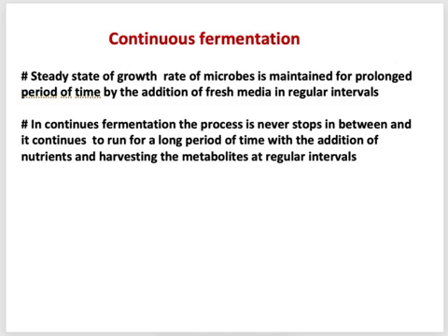Now, continuous fermentation. As the name suggests, this process will keep continuing. How can we achieve this? In continuous fermentation, we continuously put in media, the substrate. That means you continuously add fresh media or substrate into the fermenter, and at the same time you take out your product, some used media, from that fermenter.